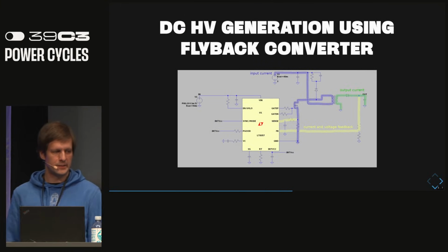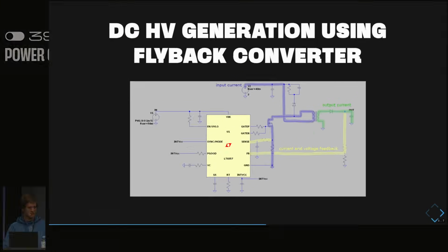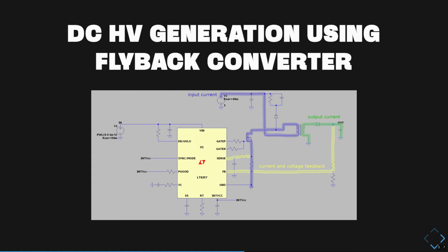All right, so the circuit idea is called a flyback converter. Basically, the good thing is you have a transformer here, and the voltage scales up with the turns ratio of the transformer. So I used a 1:10 turns ratio transformer, and that worked quite well. These types of converters are also used for high voltage applications, like in camera flashes, or if you're familiar with electromagnetic fault injection and the ChipSHOUTER, that also uses this kind of circuit design.